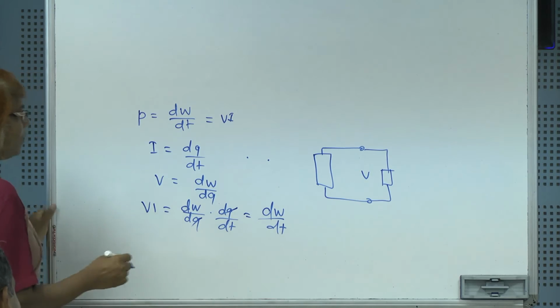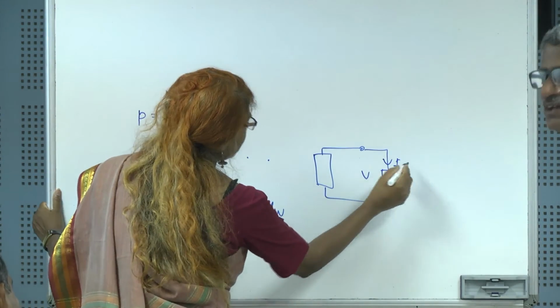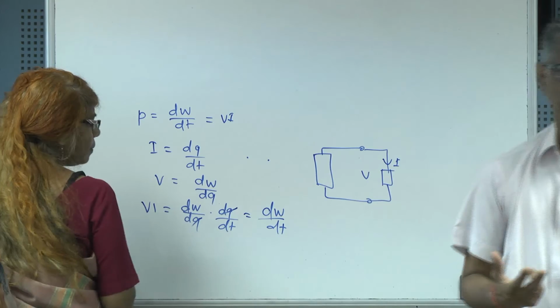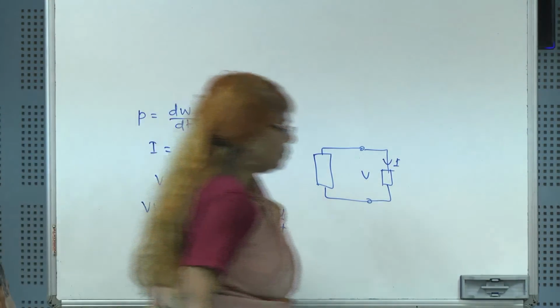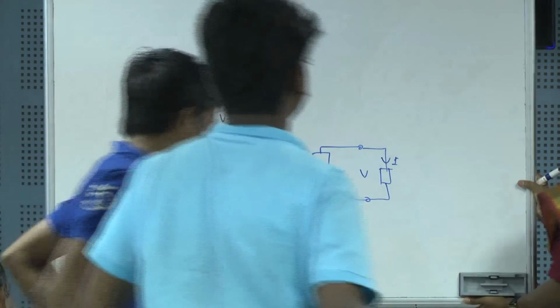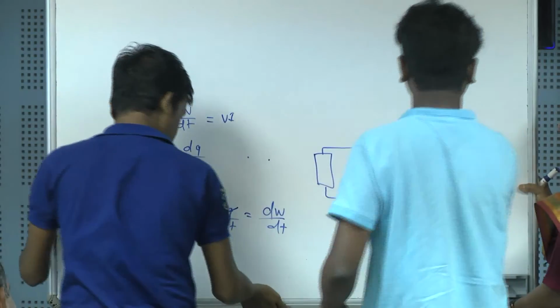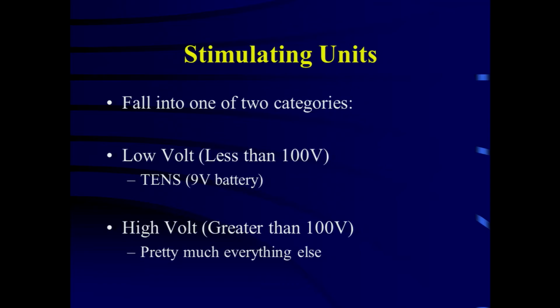A small explanation. When you start electrical circuits, we talk about current sources and voltage sources. You remember that? And nobody tells you what a practical example of a current source is. For long, at least in the beginning, you don't understand. Somewhere close to that is a triggered transistor: when the gate is controlled, it acts as a current source. And today, the photovoltaic cell is an example of a current source.